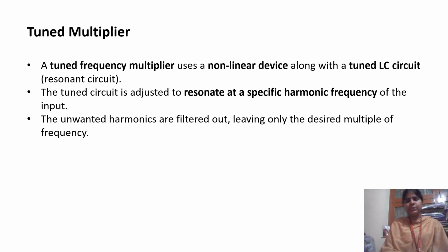Tuned multiplier. What is a tuned multiplier? A tuned frequency multiplier uses a non-linear device along with a tuned LC circuit. The tuned circuit is adjusted to resonate at a specific harmonic frequency of the input. The unwanted harmonics are filtered out, leaving only the desired multiple of frequency.